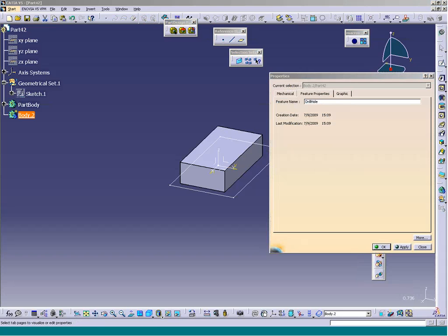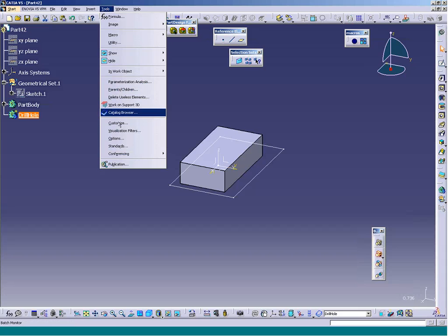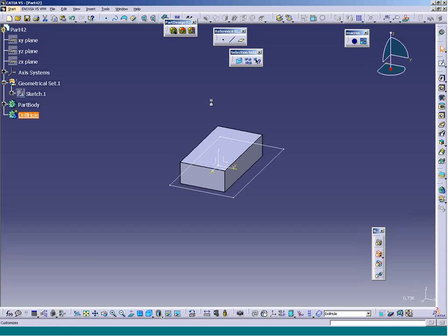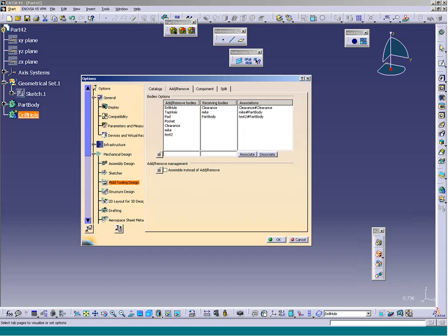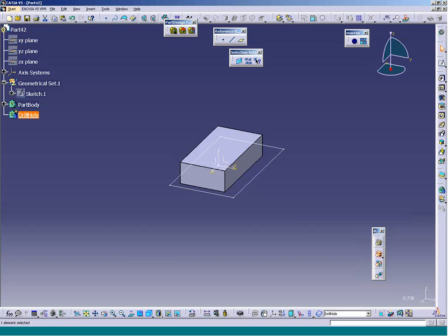As long as you keep the name drill hole, or let me show you the options here. You keep the name drill hole, pocket, pad, or tap hole, we'll keep the information tied with it. So in this case here, drill hole, tap hole, pad, and pocket are all the bodies that the software is looking for that will automatically do the cutouts. I can actually create my own bodies and link it to another body inside of another part. I don't have time to go into that, but it allows me to get very, very creative on taking information and passing it from one part to another part without having very basic CATIA skills.